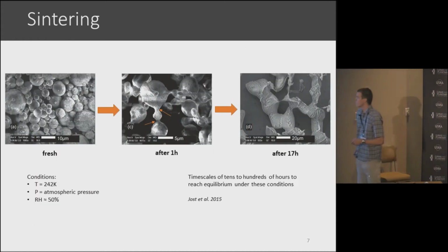So here's an example that we published in 2015 with the method that creates this 4.5-micron particle. This is just after production. We see the particles in a gray SEM image, the pure particles plus here some frost condensation. Then when leaving them for 1 hour in a normal chest freezer at -40 Celsius and at atmospheric pressure, they already start to grow together.